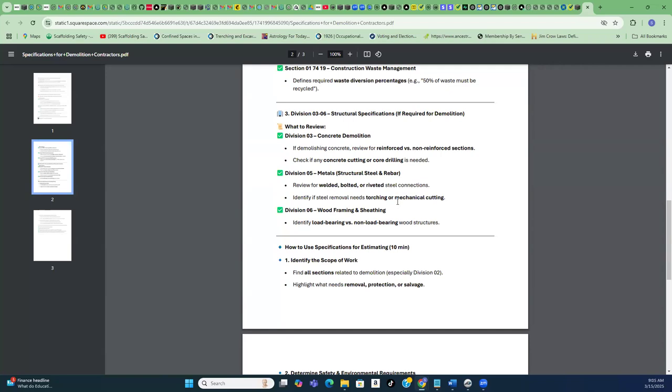Maybe for your scope of work it may or may not. But I send you an addendum always, even if you review it or not. I got an addendum on the one we're doing, and I thought I'm not going to review it, but then they said, yeah, we added doors, right? So if I'm the framer, I need to reflect on my estimate that I did review the addendums, and always say this estimate is based on plans and specifications dated the last date, whatever the last addendum they sent you, because that's telling them that you reviewed the addendum.